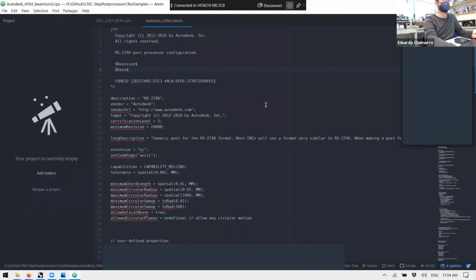That's why sometimes, when making some kinds of cuts, the post processor fails. When it fails, the machine doesn't fail. What it does is, when you load the file, it says this line, like number 7432, is not compatible. You can acknowledge and still go for it, but it might skip the line, or do something weird.